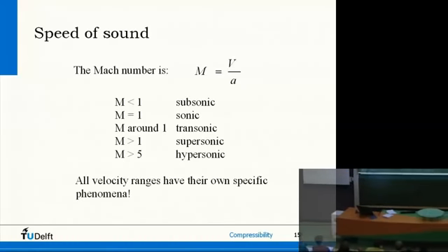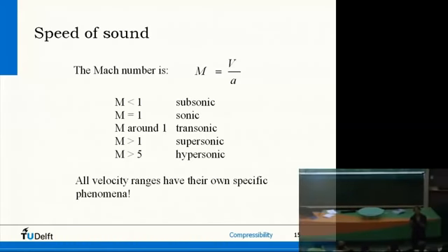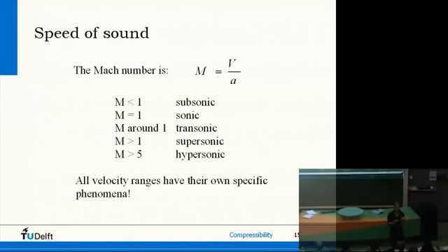But if your flow then has to decelerate again from supersonic to subsonic, the way that works is with a shock. And a shock is a very discontinuous, very sharp location where all your properties jump: temperature, pressures, velocities. And that is not an isentropic effect. So you can only apply the isentropic relations up to a shock, but not over a shock. Over a shock, your total temperature and everything changes.